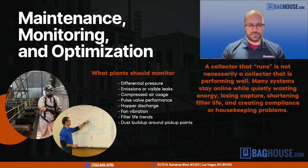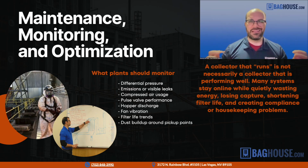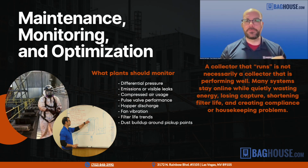So if you have a dust collector where you see a lot of dust forming at the pickups, or it's just dusty in your plant, you have to look at the whole system and find out where the problem is. Not often just that the baghouse is not doing well. It's often a victim of other things. So being able to diagnose and troubleshoot problems from a systemic perspective is really essential to making sure that you get the best performance out of your systems.